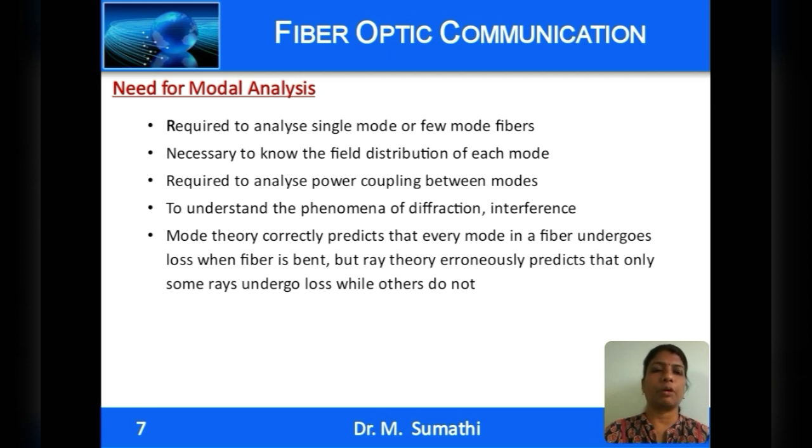When light propagates in a fiber, power coupling between the various modes occurs, and therefore modal analysis is required. Similarly, it is needed to analyze diffraction and interference. And when a fiber is bent, ray theory says that only certain rays are affected, whereas other rays go unaffected, which is wrong. Mode theory correctly predicts that when a fiber is bent, all the modes in a fiber undergo loss.